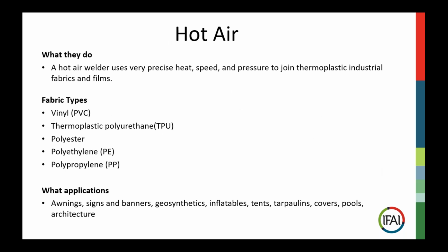So what is hot air welding? Well, it's exactly as it sounds. You're using hot air to weld two thermoplastics together, and this is in a numerous amount of applications. Some of the fabrics that can be welded are very common PVC or vinyl, as it's commonly referred to. Other thermoplastics like polyurethane, polyesters, polyethylene, polypropylene.